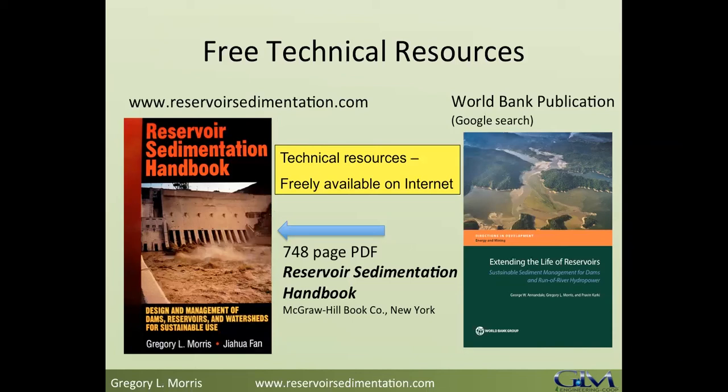And if you have, for instance, the Western US, where you have a climate where these storms are more episodic, the off-stream reservoir will be less appropriate from the hydrologic standpoint, simply because you end up having a very, very large diversion line into the reservoir, and you're trying to divert so much water that you're going to take so much sediment with it that it doesn't make any sense.